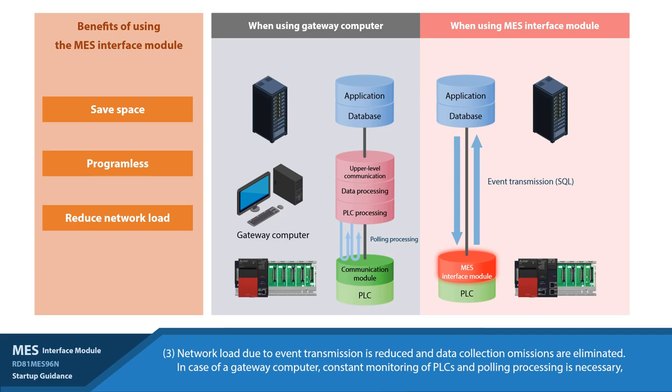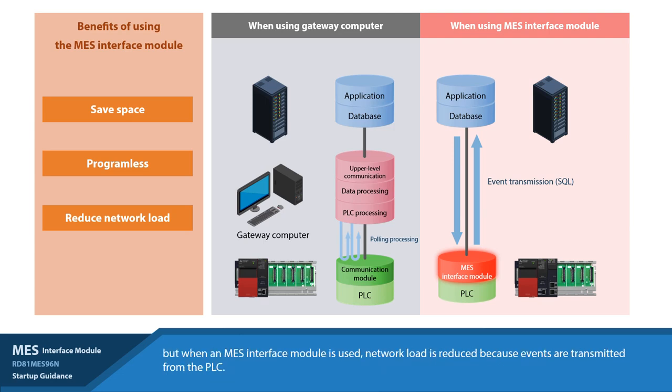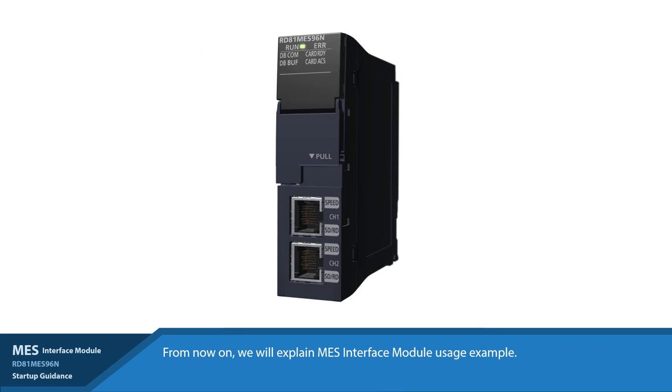To this point, when using a traditional gateway computer, constant monitoring of PLCs and polling processing is necessary. But when an MES interface module is used, network load is reduced because events are transmitted from the PLC. Next, an application example showing how an MES interface module can be used.